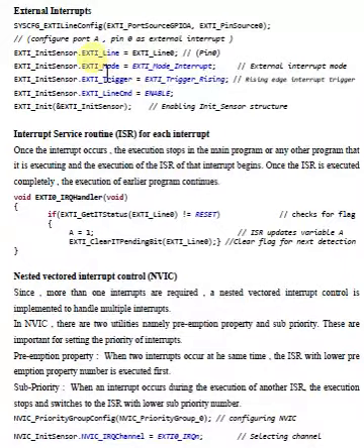First, you have to configure the port, which port you want to have these interrupts on, and every microcontroller has its own interrupts mentioned on different pins of different ports. For example, I have taken here port A and pin 0, and I can give the type of interrupt. So it's an external interrupt mode, and then a rising edge.